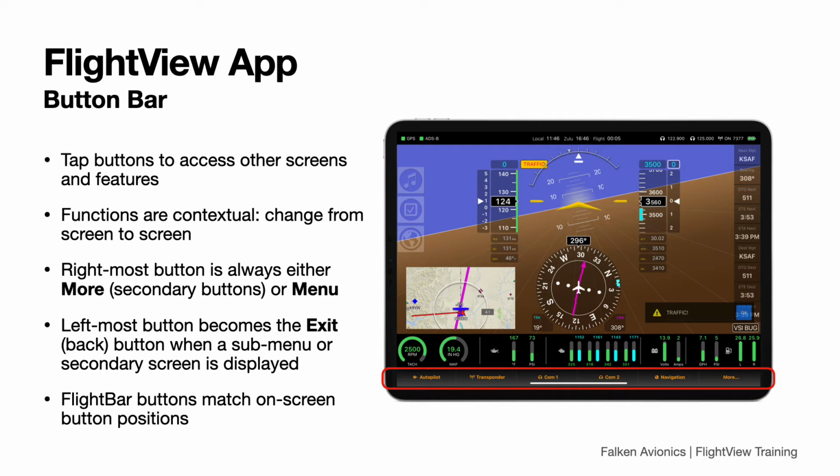For example, if you were to tap the COM1 button, the system would load the COM radio screen, and the buttons would update to show COM radio related options. Most of the time, the button bar shows the main menu. For more options, you can tap the 6th button marked More. This loads a secondary list of menu options. When you're in a secondary menu, or when you have a secondary function active, you can return to the main menu and dismiss the secondary screen by tapping the first button, which is marked Exit.